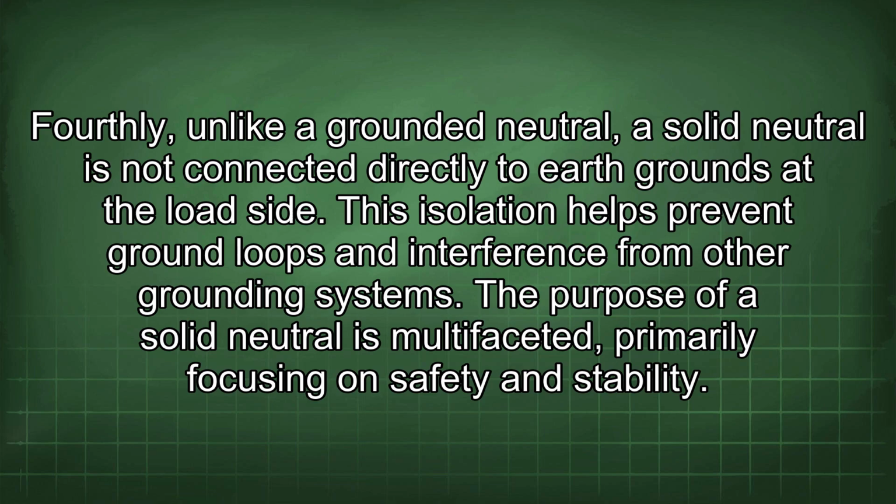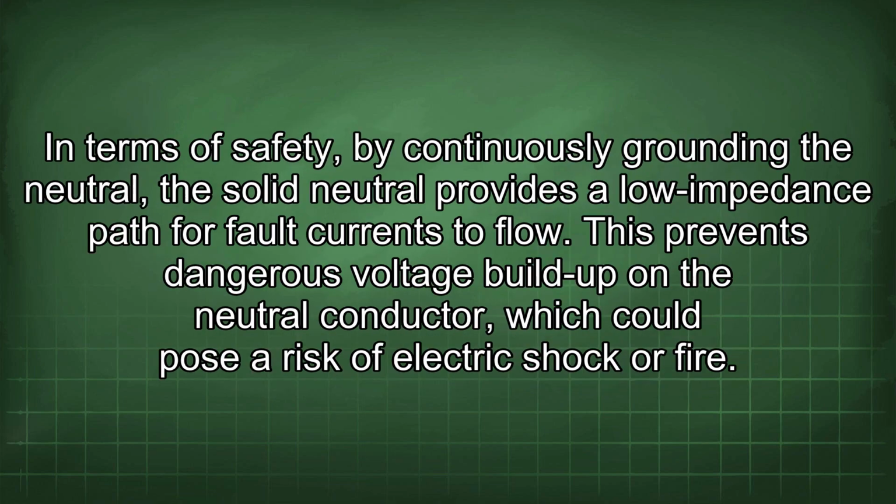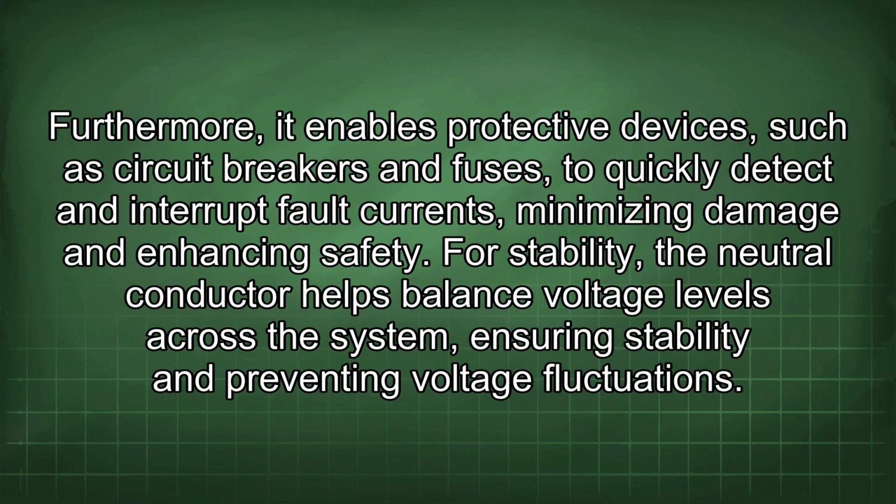The purpose of a solid neutral is multifaceted, primarily focusing on safety and stability. In terms of safety, by continuously grounding the neutral, the solid neutral provides a low impedance path for fault currents to flow. This prevents dangerous voltage build-up on the neutral conductor, which could pose a risk of electric shock or fire. Furthermore, it enables protective devices, such as circuit breakers and fuses, to quickly detect and interrupt fault currents, minimizing